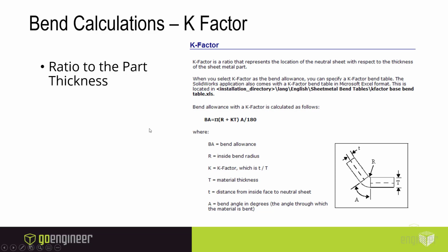factors, a lot of times there's a little trial and error in the beginning, where you take a known part and build it in 3D, measure it in 2D, and then use that to reverse engineer what your calculation or your K factor is based on how your machinery works, how your press brakes work, or if you have CNC tools. There's a lot of variability when it comes to sheet metal and a lot of looseness when it comes to the tolerances typically as well.